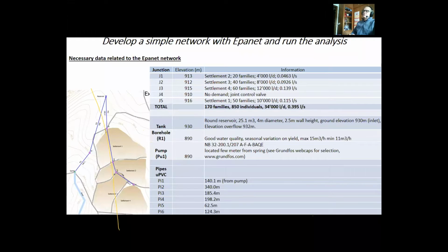And then you have to choose a pump. Even that, the pump depends on the elevation that the water has to be pumped, and then on the quantity of water that has to be pumped. The thing is that if you want to pump all the water for one day in a short time, you need a big pump and a big tank. If you want to pump the water over many hours, you might need a smaller pump and a smaller reservoir. This is a fine tuning that we are going to see later when we do time analysis.